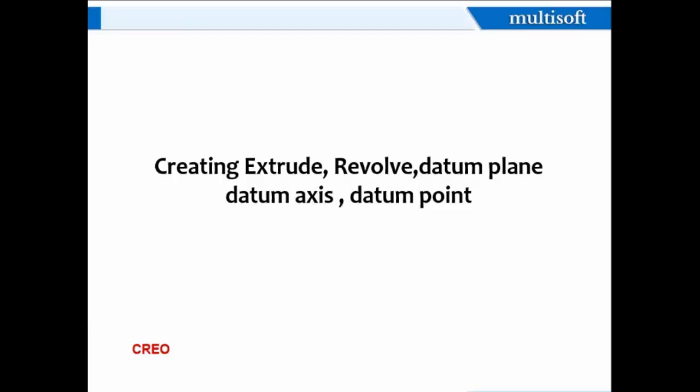First of all, you have to construct the basic sketches for any 3D model feature. Then after that, you will create the extrude feature. Extrude is basically providing the third direction, which will be Z. Right now you are working on two planes, two axes. One is X, second is Y, and Z is missing here. Now in extrude we are providing the Z axis, right?